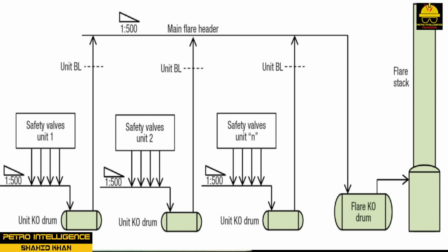Thermal relief valves are provided to protect against thermal expansion as required in liquid full service. The flare and relief systems are designed in accordance with applicable regulations and practices to protect equipment and personnel against overpressure situations. Many units that process volatile hydrocarbons have two collecting systems, a warm-wet system and a cold-dry system.